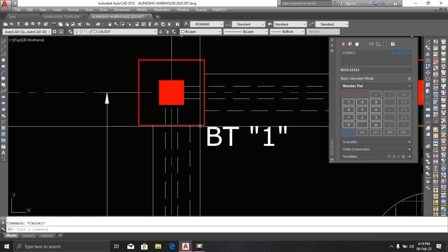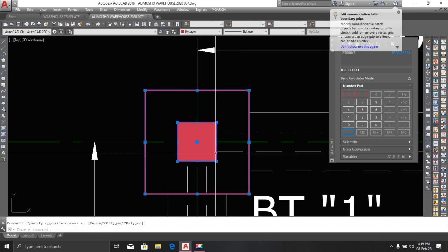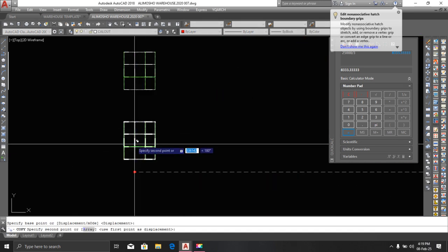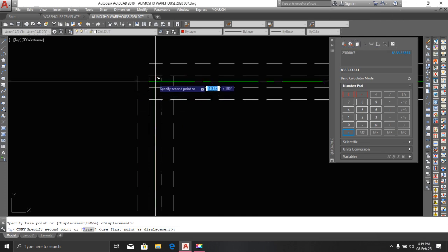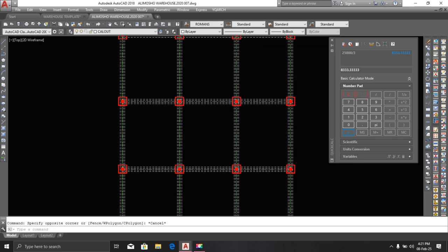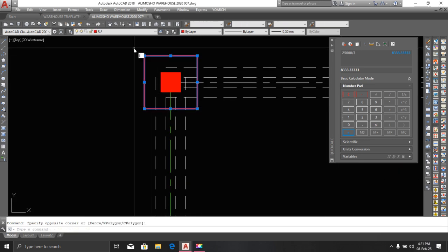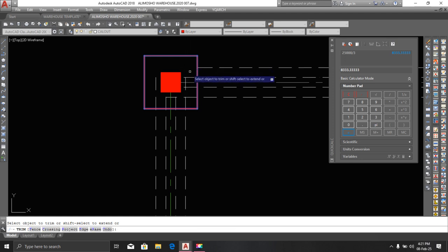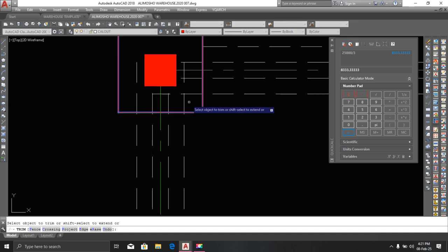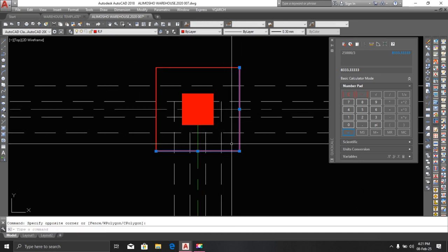So I'm going to pick this up now and place it in my layout. So I like it like this. See, on spacebar from the center, we have something like this. All right, so now we're done with the insertion of the pad base. So the next thing for you to do is trim this out, the center out. Click on the box, click on the pad base area, TR spacebar. We have something like this. Trim it out. Go to the next one.